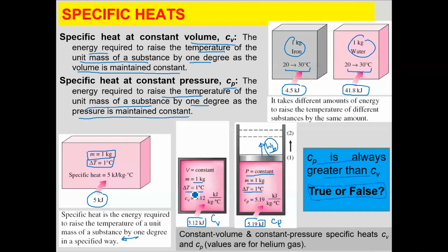Very good. So in CV, I'll not go to internal energy at the moment, but yes, in CV, since dV is equal to 0, your PdV or boundary work is essentially 0. Your system does not have to do any work against the movement of the boundary.